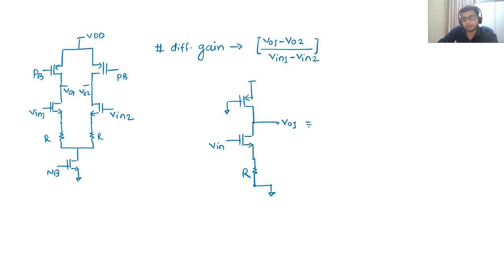So for this circuit, what you can see, if I want to see the R down. One thing that I want to tell you here, first for calculating this gain, V out 1 by V in 1, where V in 1 is nothing but plus V divided by 2, that I call differential voltage, from the small signal point of view. So what is this? Every circuit has, as we know, GM R out. GM is the short circuit transconductance, and GM for this circuit is nothing but GM of your input pair, or input transistor.